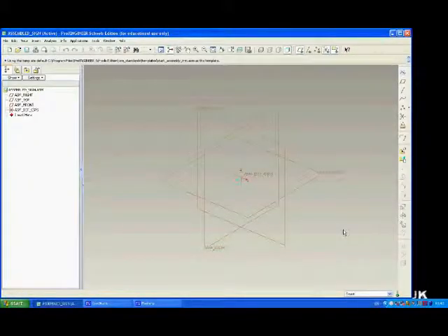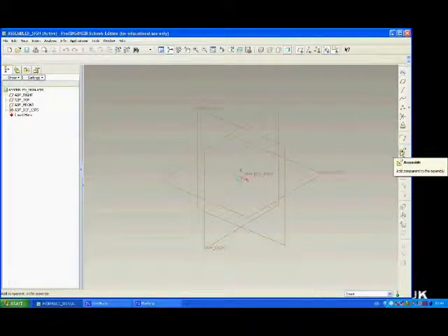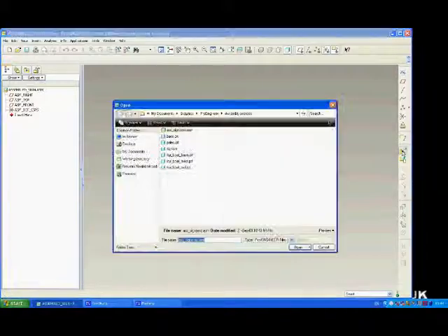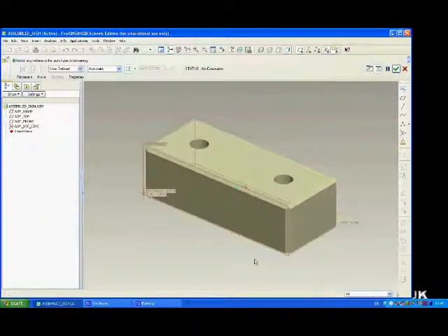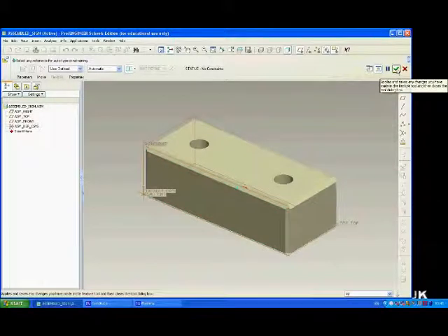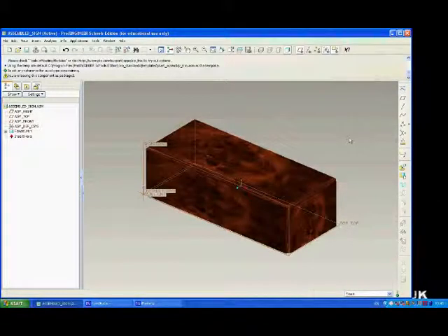This is the screen you'll see as the assembly document. Most important icon is this one on the right hand side, the assemble icon. This allows us to add new components into the assembly. Make sure you click on that, and make sure you have the folder open which has base, pulls and sign in it. The first thing I'm going to add is the base part. So select base and then select open. Now you should see this view on your screen. We don't have to do anything with this at the moment, so we're going to click the green tick and accept it as it is.